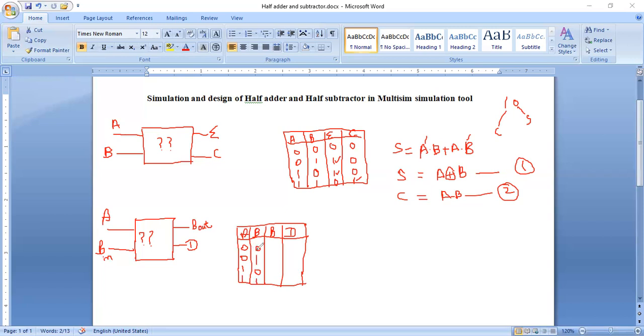Let's start the operation. When we subtract 0 from 0, we will get 0 and 0. Now this is a very important thing. You cannot subtract 1 from 0. In that case, please note that we need to take a borrow 1. Before that we had 0, and now with the borrow 1 it is basically 2. Now we subtract this 1.